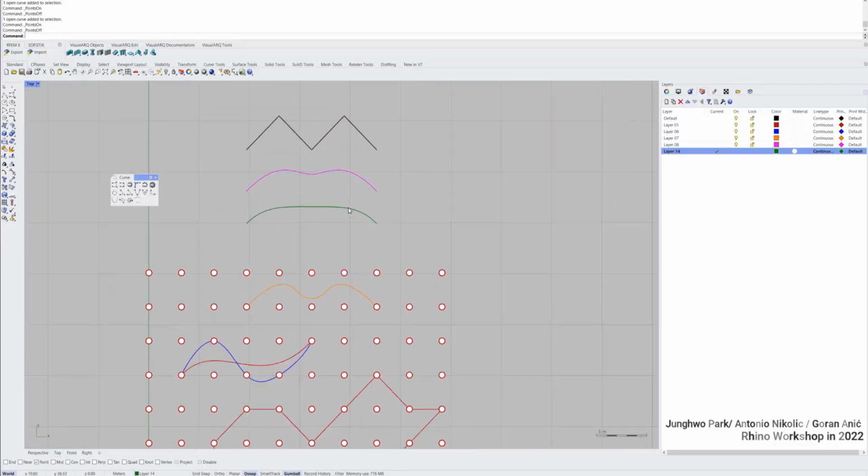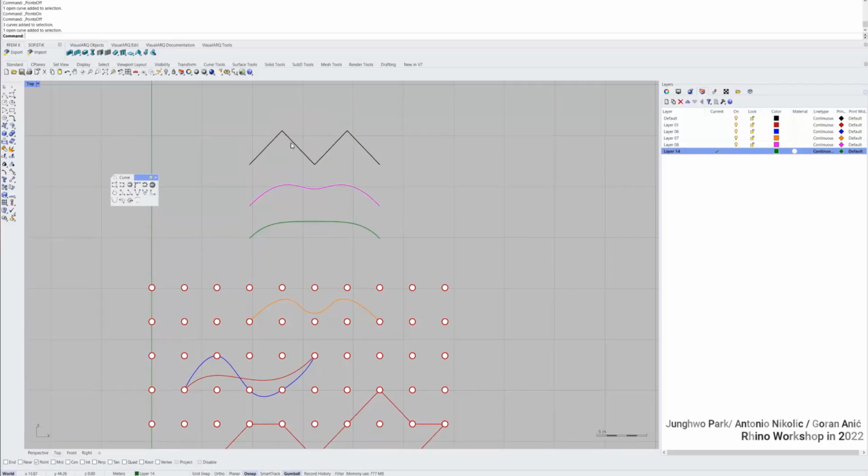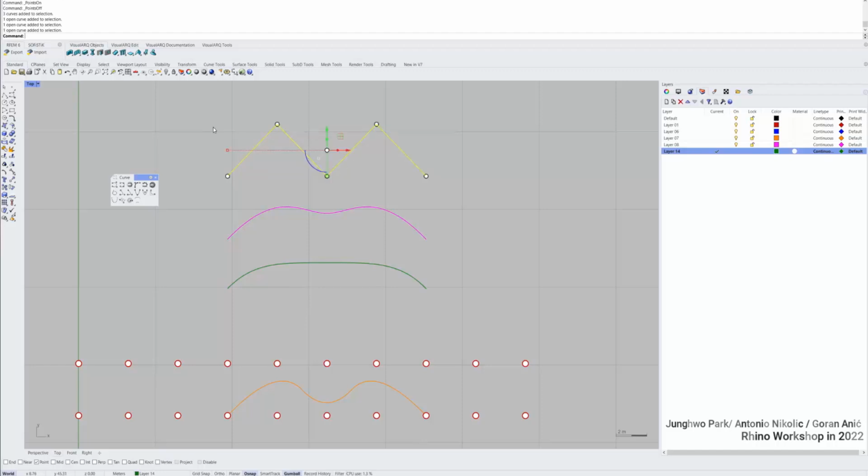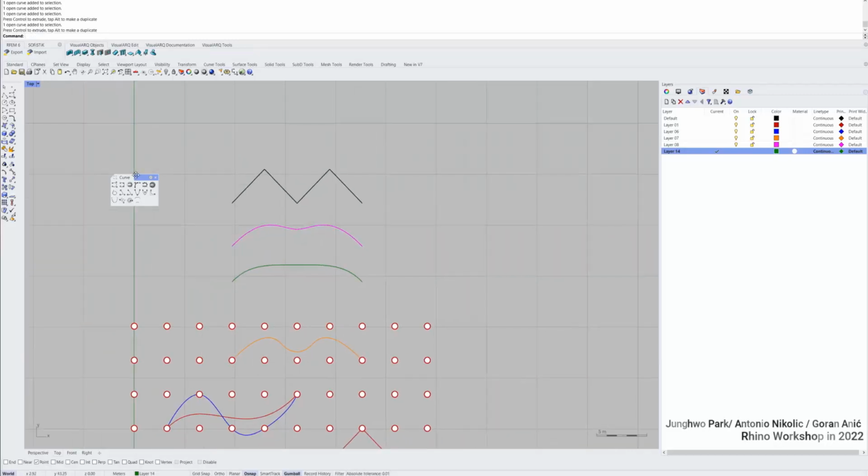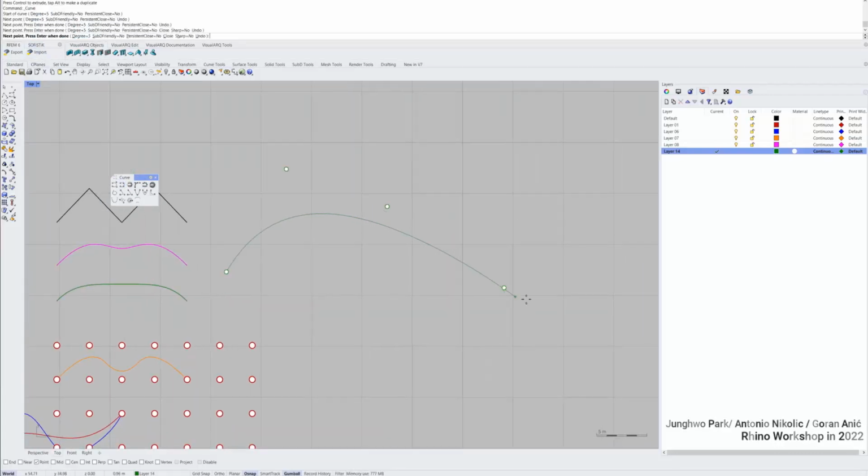So yeah, you can certainly choose a different degree when you're working, but I would say when you work with a structural model that you calculate, and you consider it an analytical model, then degree 1, of course. And when you consider very smooth NURBS surface modeling, degree 3. For automotive, or let's say this is the street axis, then degree 5 gives you a better result, but that's what I heard. So I don't know.